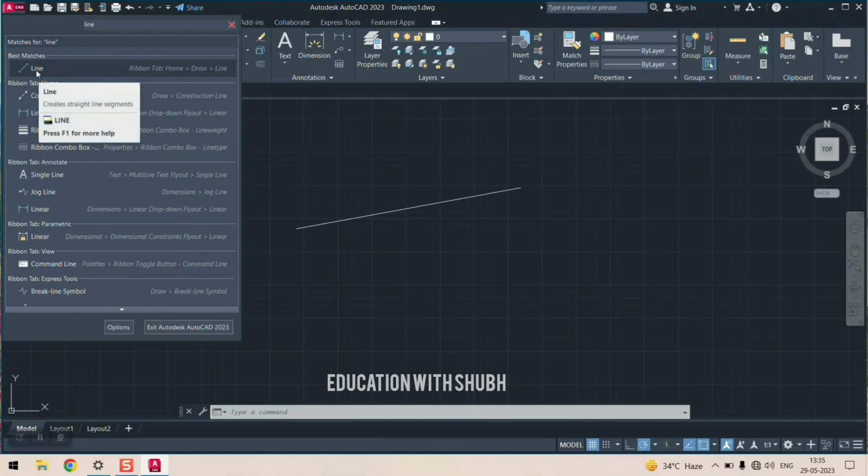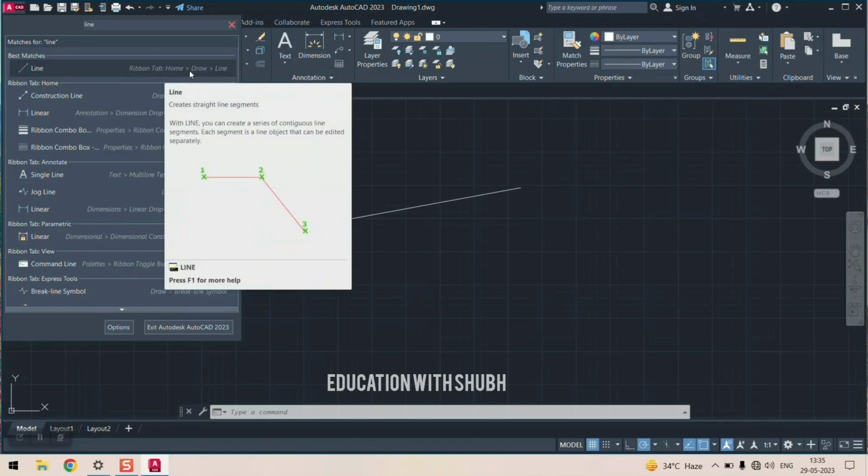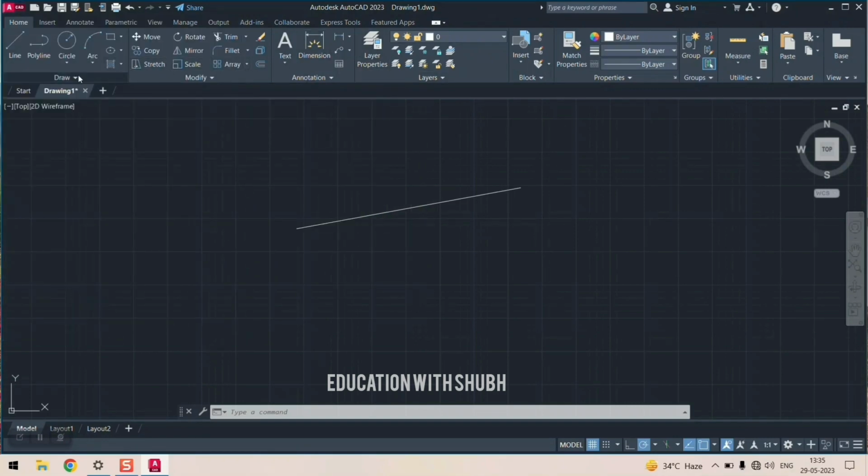This is line, it simply means that you have to give the line command directly to the command line. This is a command for a particular standard operation, the operation which you want to do. And this is the location. This is your manual location of that particular command, inside the Home tab, inside the Draw panel. Inside that there is a line command. If you forget something, like you don't know where the line command is available, maybe it is available in the drawing side, maybe it is available in the modify. This is just for illustration purposes.